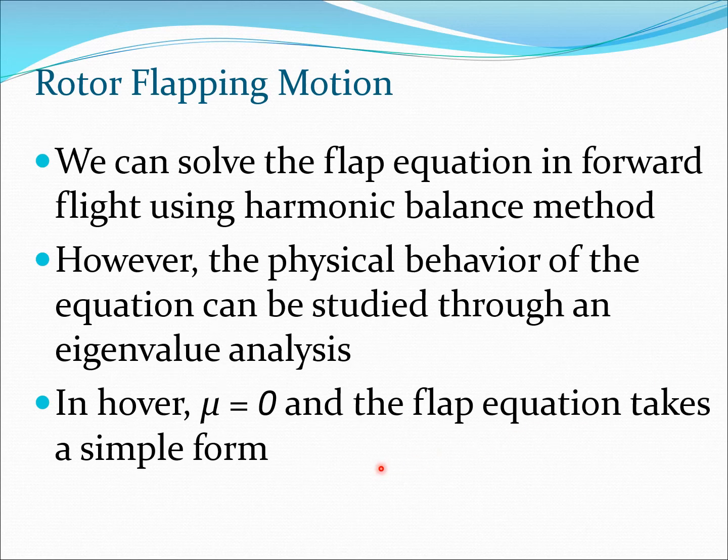Now you know the flap equation which we have obtained is a periodic differential equation. You could take the motion dependent forces to the left hand side, and then you could solve this flapping equation using the harmonic balance method. So remember the harmonic balance method, you substitute beta psi as a Fourier series. You assume beta psi is beta 0 plus beta 1c cosine psi plus beta 1s sine psi and continue like that,